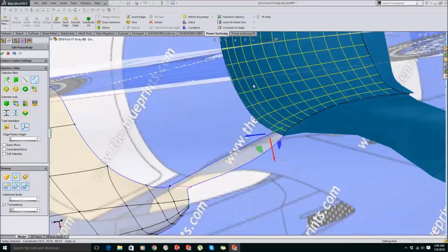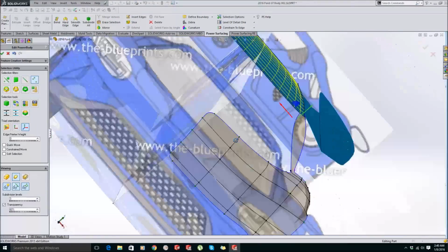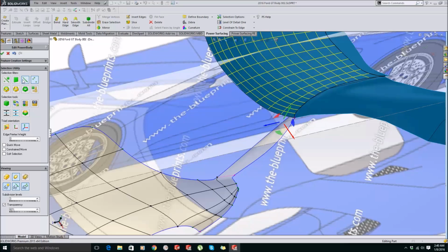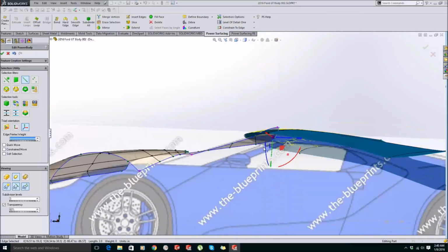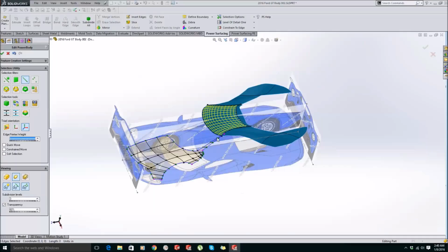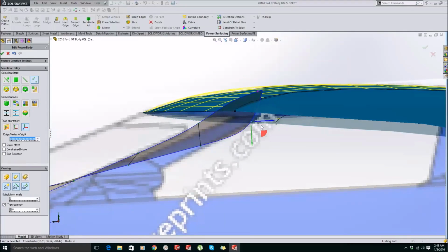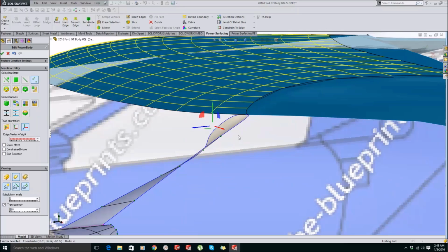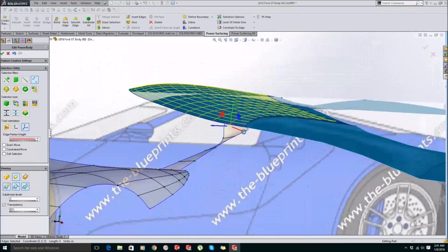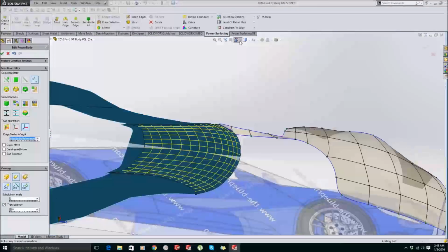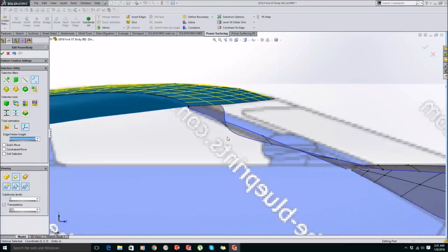You have to bring the vertex closer to the reference geometry in order to apply the constraint. If you bring it nearer to the geometry, the constraint you apply will easily be applied. When you click on the constraint to vertex, the vertex is constrained to the nearest vertex of the geometry. If you select edge, it will constrain to the nearest edge of the geometry. As you can see, I have applied it, and both of the vertices of this link are connected to the roof.